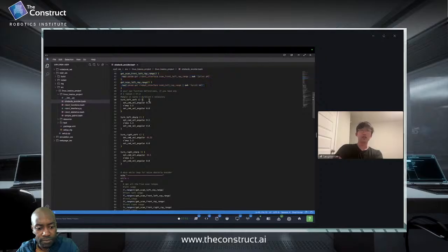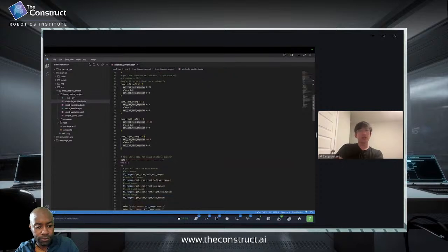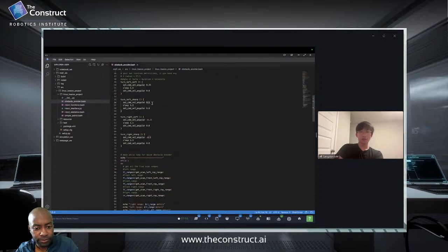And then I created my own thing, where I want to be specific for the angles for different situations. So I'll explain that later, but when left or right is blocked, when the front is not blocked, I'll try to command the robot to turn softly. And then when everything is blocked, then I try to say turn sharp so we have more space. And then it's a 0.5, sleep 2.3 seconds.